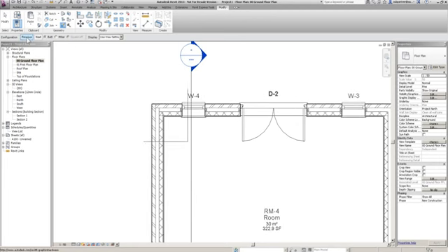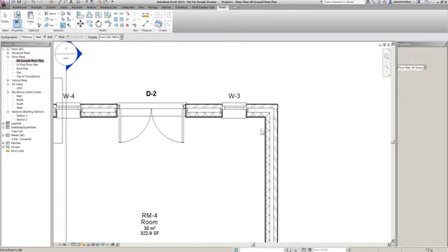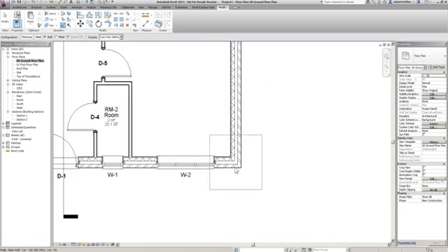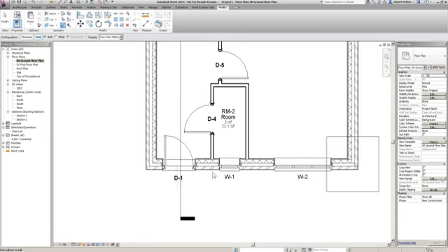I'll go to a butt, and then I'll just press next or previous, so that now this wall's butting into this. Basically, because this wall here was butting into this wall, and this wall's going up, there was a little gap at the top of this wall. I'm going to change this one. That one looks all right, so that one should be fine. Okay. Let's come down here, look at that one. We're going to have the same problem there. Now, okay, that's all good. Let's change it to this one. And again, just there. Done.